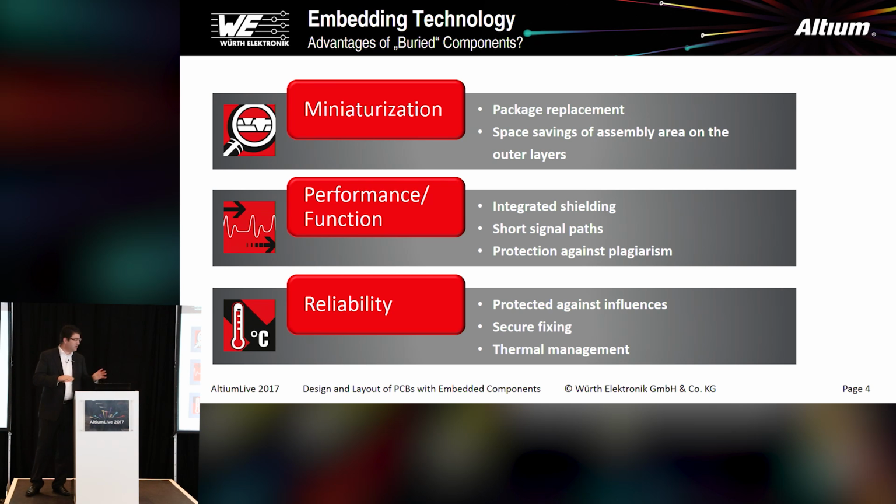So when you look at the worldwide global trend, the package replacement is one part, especially well used nowadays in the smartphone industry, as well as the short signal path. For example, everyone of you who is using an iPhone of the newest generation or a Samsung smartphone with an Exynos processor is actually using that technology. Because in the processor substrates, you will find the decaps already, so that Samsung and Apple do not need them anymore on their main board. So you're using it already.